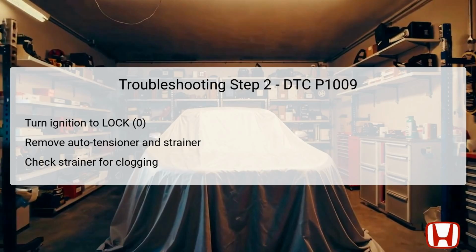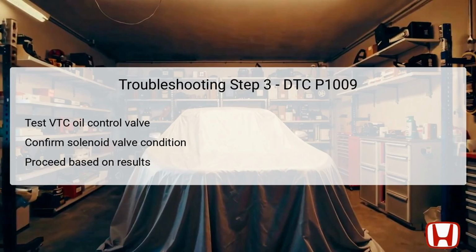Should clogging be evident, take immediate action to clean the strainer and replace the engine oil and oil filter as necessary. The third step involves checking the operation of the VTC oil control solenoid valve, a crucial component in the VTC system. This solenoid is responsible for regulating oil flow to the VTC actuator, affecting camshaft timing and operation. Use appropriate diagnostic tools to test the solenoid valve for proper function. An insufficient response indicates the valve is faulty.